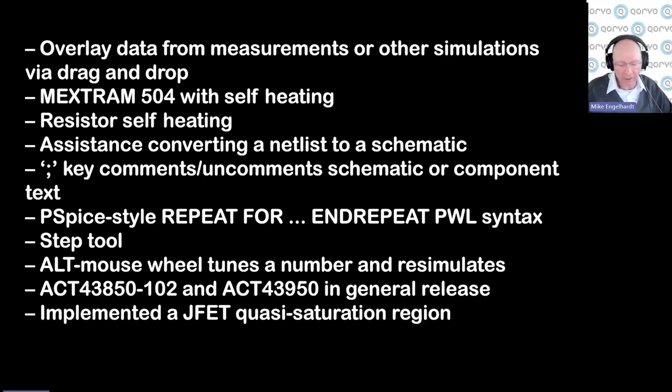And the JFETs that were in an integrated circuit tended to have a lot of production scatter, and they were only used in the saturation region, not in the triode region. They weren't used like resistors. They were used like current sources to a small extent, or as pinch resistors.